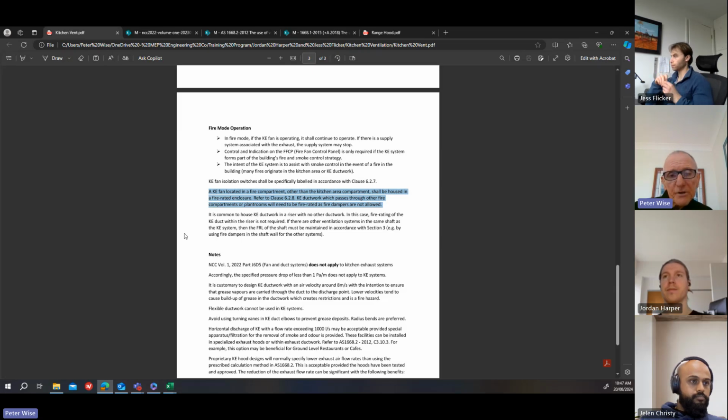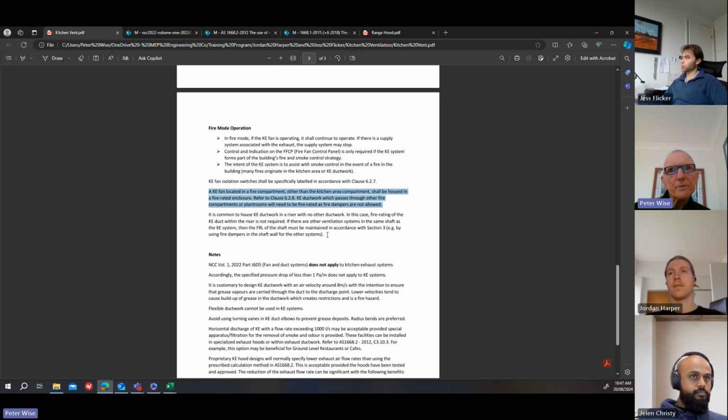For instance, they might ask you to put in stair pressurization in a building that doesn't require it by the NCC. Or they might say, the NCC does require stair pressurization or smoke exhaust, but under my modelling scenario, you don't need it because we're going to do something different, which might be sprinklers or an electronic fire alarm system or something else. That's just by way of clarification, but we'll talk about that another time.